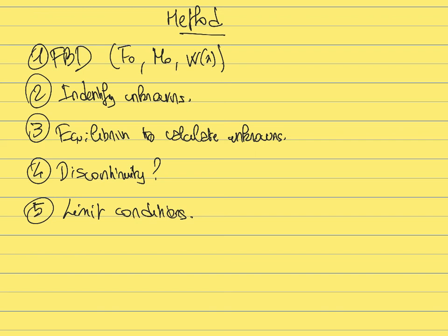We will see some examples of this when we talk about some application problems. But here, step 5, you will need to identify the value of the external forces and external moments at the two edges. That is going to give you some constraints for the value of the internal shear and internal moment at the two edges, which is going to give you some equations to calculate the integration constants.